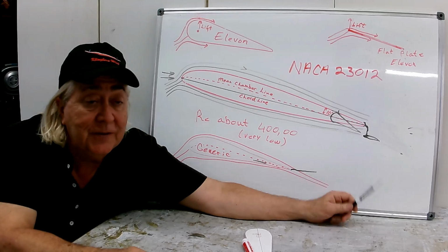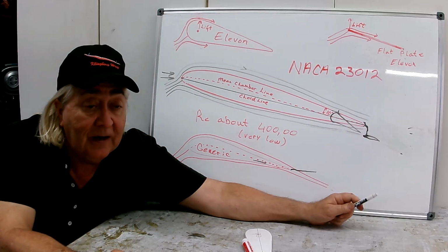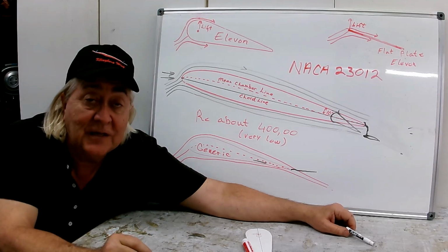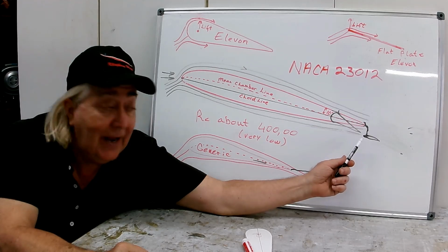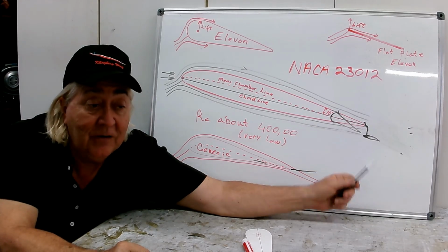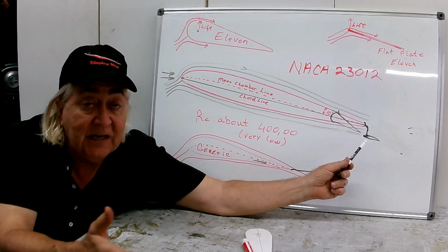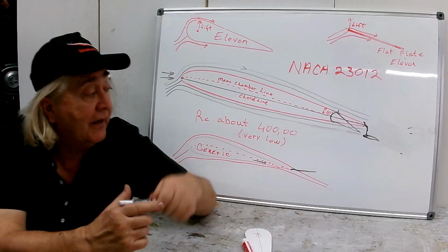When you're flying slow like the Mitchell wing probably never went more than 45 miles an hour. Not as much of a problem, but the drag goes as the square of the velocity. When I go 100 miles an hour, that's a lot of added drag. Will I go 100 miles an hour? Maybe, someday, who knows. But even 60, 70, you're paying a big penalty on drag. So these guys are very effective, but very draggy.